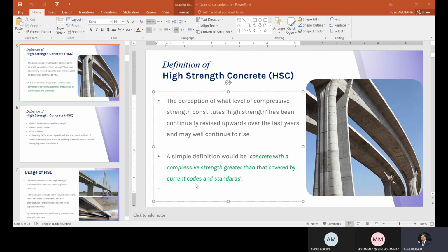The only difference is in the 10 kilograms of aggregates. For the first one, they use the size ranging between 4.75 up to 14 millimeters. The second one uses 10 kilograms of aggregate with the particle size ranging between 4.75 up to 20 or even 22 millimeters, but the same contents.